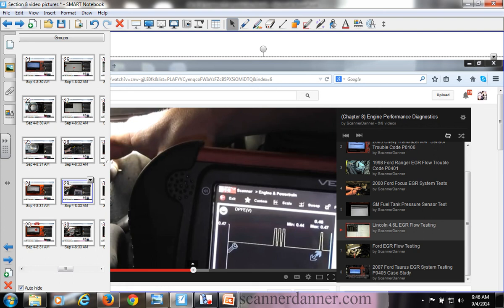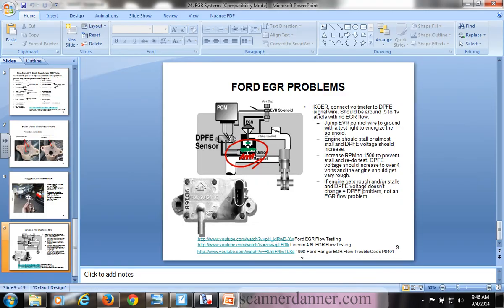You see when you're checking a sensor, it's more than sometimes just wiring. It's more than 5-volt ref signal and ground circuit integrity. It's also what makes the sensor change. In this case, it's the EGR valve. If that EGR valve never opens, pressure is going to stay the same here, and the signal voltage in our case is going to stay at 0.45. It never moves. That's not a fault of the sensor, that's a fault of EGR flow.